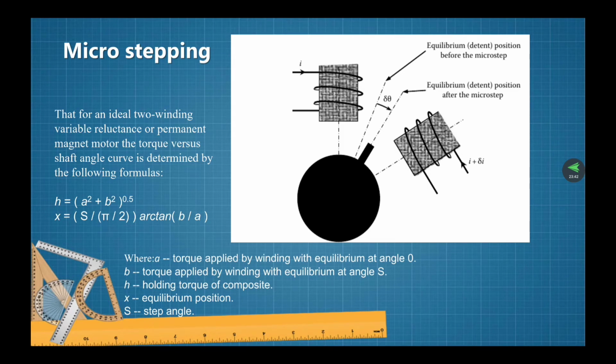Okay, although some microstepping controllers offer over 100 intermediate positions between steps, it is worth noting that microstepping does not generally offer great precision, both because of the linearity problems and because of the effect of static friction.